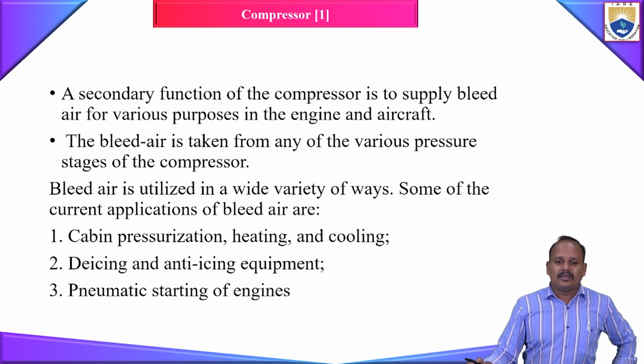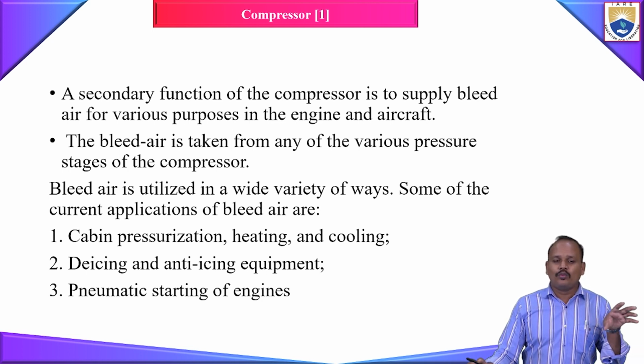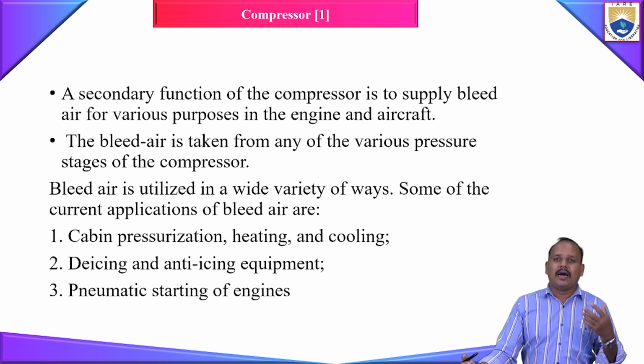So de-icing, you see, when your aircraft is flying at that high altitude, if there is too much moisture content present in the air, when it moves over your aircraft surface, what is going to happen? It is going to create ice. Once your ice forms, it is going to change the contour of your entire wing surface, which is going to affect its aerodynamic performance. So we have to de-ice that, that is, we have to melt the accumulated ice.